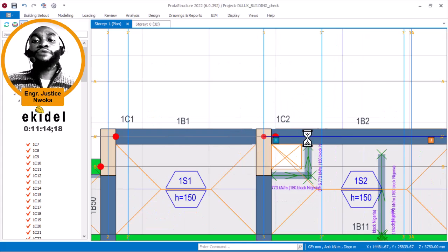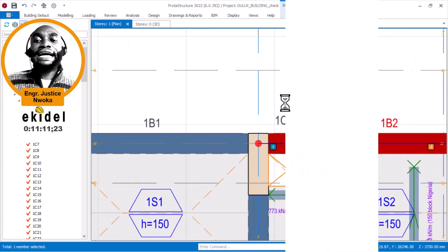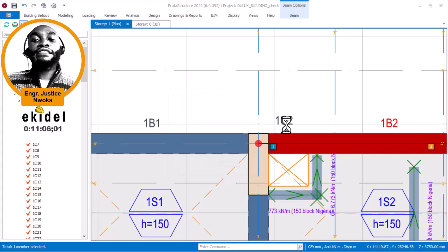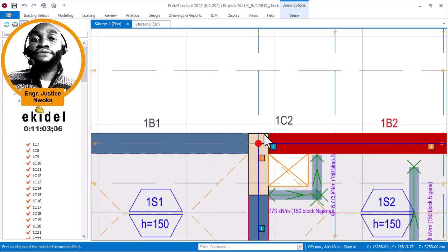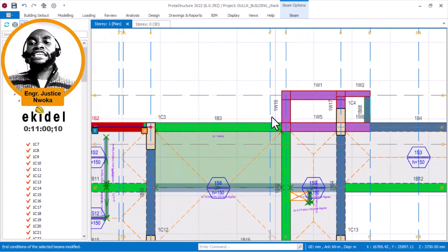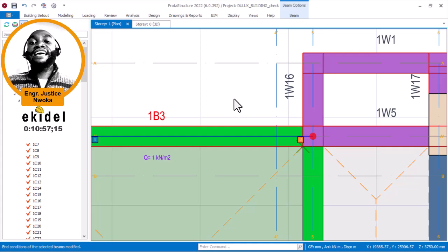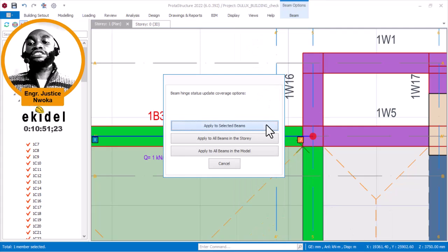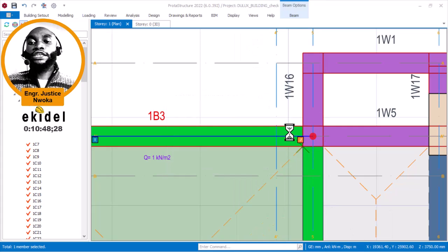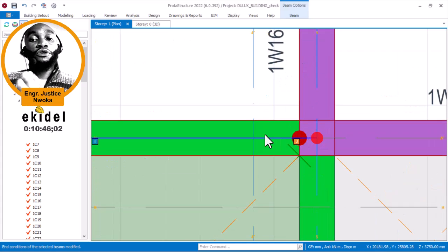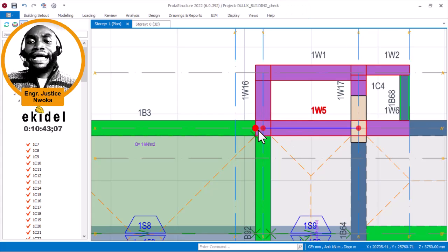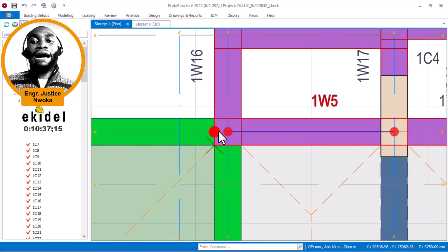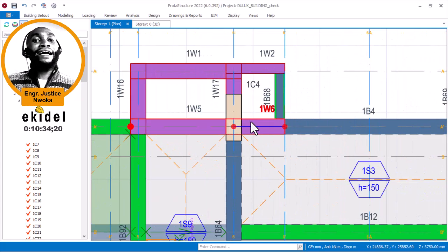Okay, so in that case right now, I'll click back on this beam and right click and then do no hinge. Okay, no hinge. So by applying this no hinge right now, it takes here to be a fixed end. Okay, that's fine. I'll then move to the last part here, right click here and say hinge at J, which is the J end, and you are now going to see the 0 appear here, knowing that the moment here becomes 0. Okay, now I did this because this is a wall. If this was a beam, I'm not going to hinge this end here. I'll continue till where I find the next one.